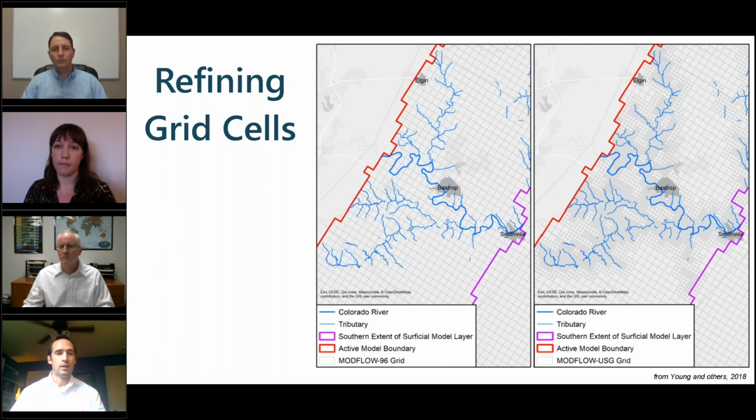Again, I don't want to go into other discussions, like groundwater surface water interaction, too much yet, but cell size does have a strong influence on simulating, say, stream flow. If you're using the river package, the simulated river, of course, occupies the entire cell. So in a regional scale model, like many GAMs are, there can be a substantial mismatch between the actual river width and the underlying grid cell, which creates errors in the simulated water table and then in seepage as well.